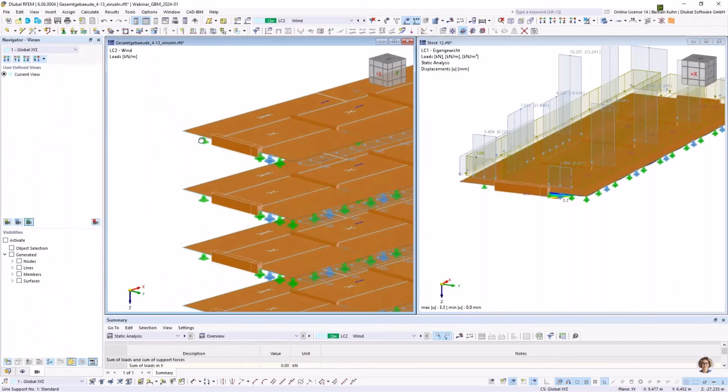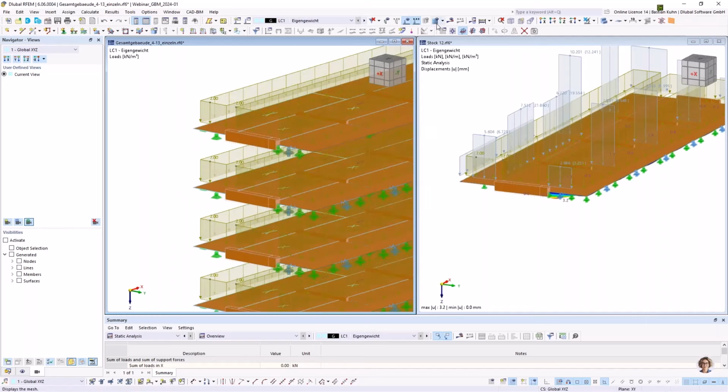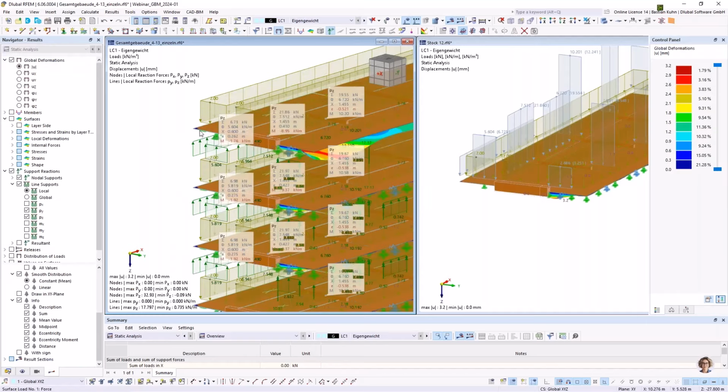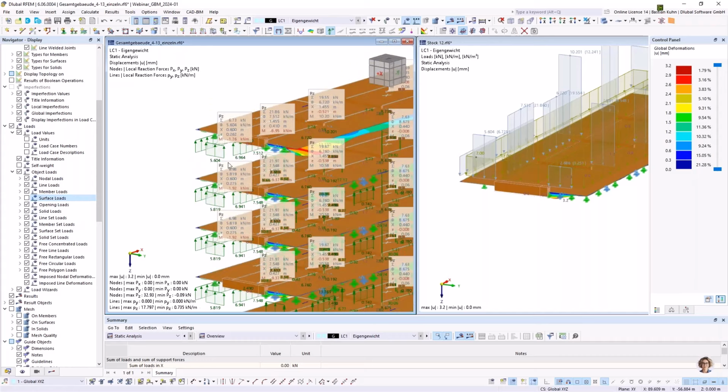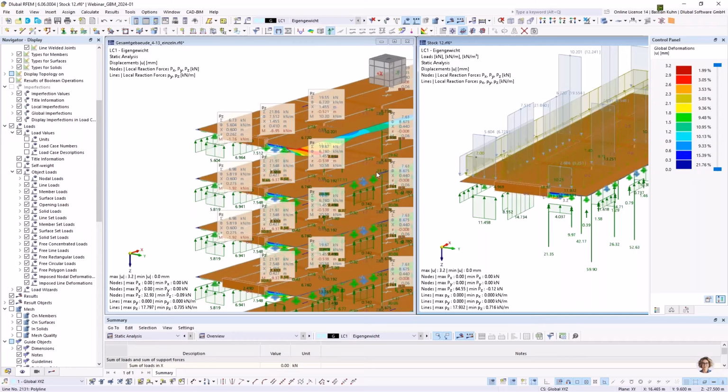And when we look for the results in load case 1 in here, so you see that this value we have in here, 5.6 surface loads is the resultant here. And of course, you also have it on the story 12, 5.8, but as this is not regarding the load transfer from the top, this is already the error what you are doing here in this 2D model, because you are not taking the force from the story 13 to the story 12. This you have to do in this separate position.